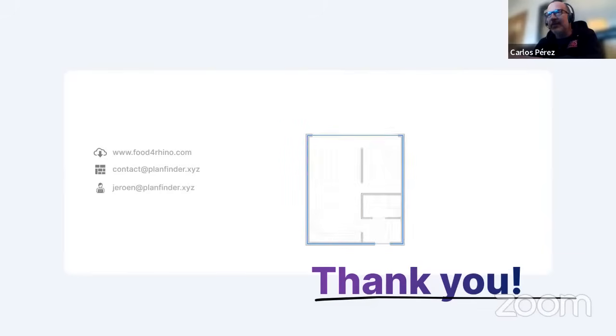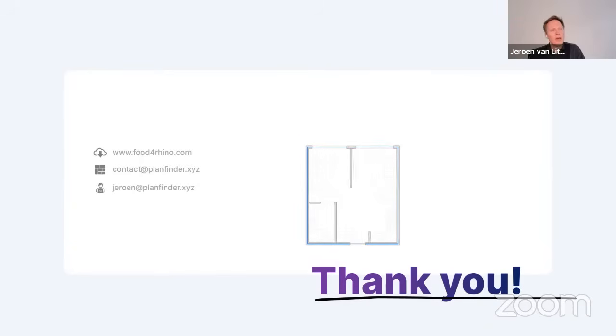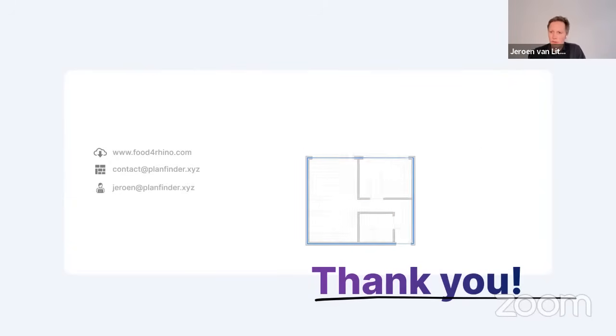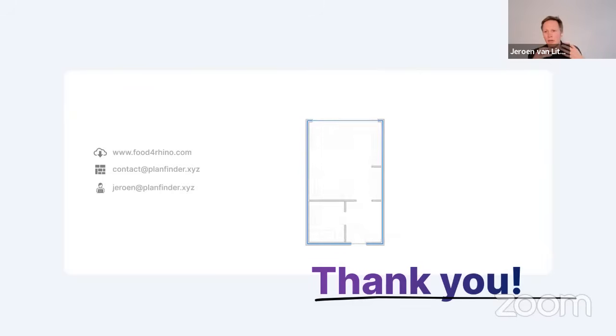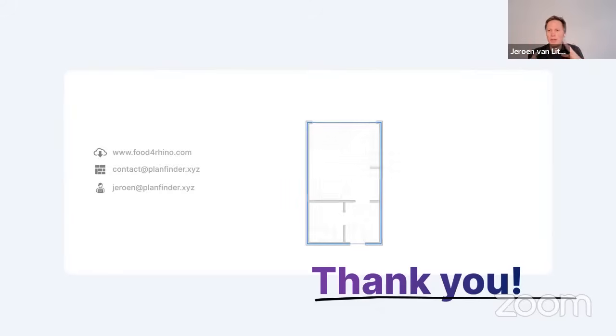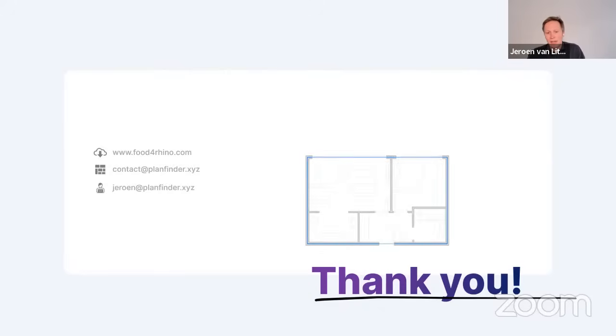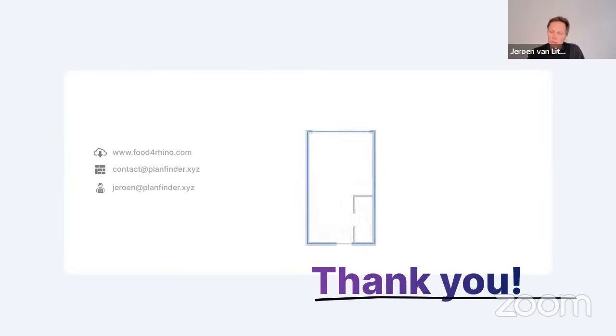Okay, this question is a bit... What's the difference between the plugin for Rhino or the Grasshopper add-on? Yeah, it works a little bit differently. First of all, the Grasshopper plugin only has the fit functionality, and the Rhino plugin has the fit and the furnish functionality. Secondly, how you play with the floor plans is slightly different. In Rhino, there's a pop-up window, and you can interact with the plans in that window. In Grasshopper, you can play with it through sliders. So you have to find out which one you prefer, I suppose.